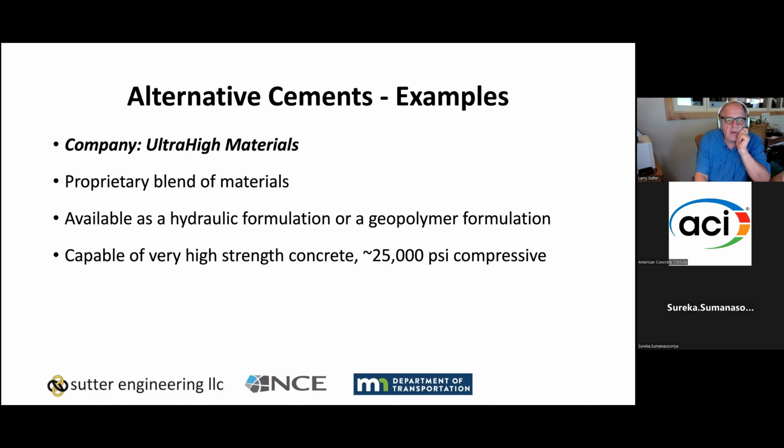And again, Ultra High Materials has a very proprietary blend of materials. They have 2 different formulations. One is a hydraulic cement, that's the one we use. They also have a geopolymer formulation, and they are capable of very high strength. It is probably designed more for structural uses, with very high compressive strength available. One of our challenges with this material is trying to get the strength down into the range where we'd want it for a paving material.